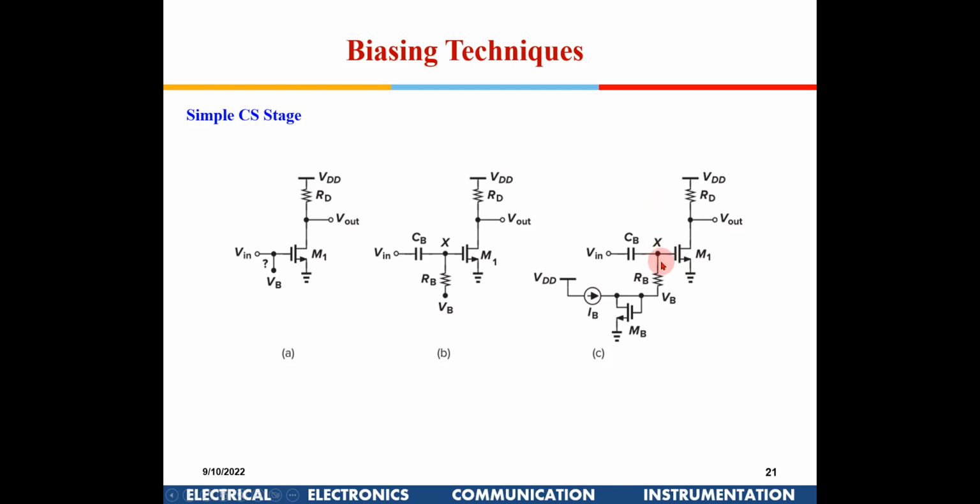When we made a CS amplifier, if you remember, we had put R1 and R2, right? Yes. But we also learnt that when we make R1 and R2, there won't be any bias stability. Then we introduced one more resistance on the source side, and then we saw that gain is deteriorating. Then we put one capacitor. So instead of doing all that, instead of one resistance here and a bypass capacitance, I remove all those things. Now I have a standard reference signal out here. I am giving a good biasing voltage here, so there is bias stability also.